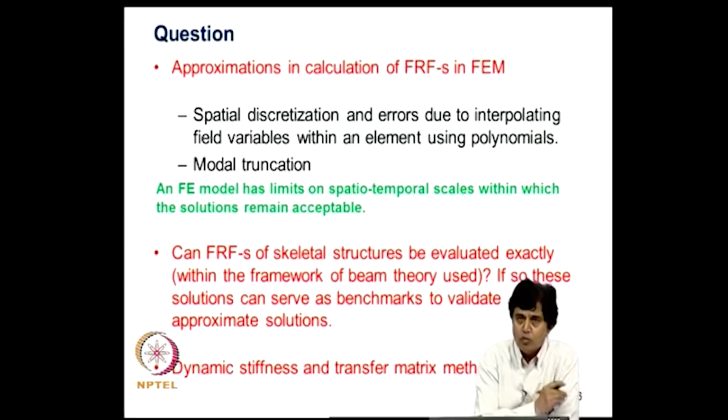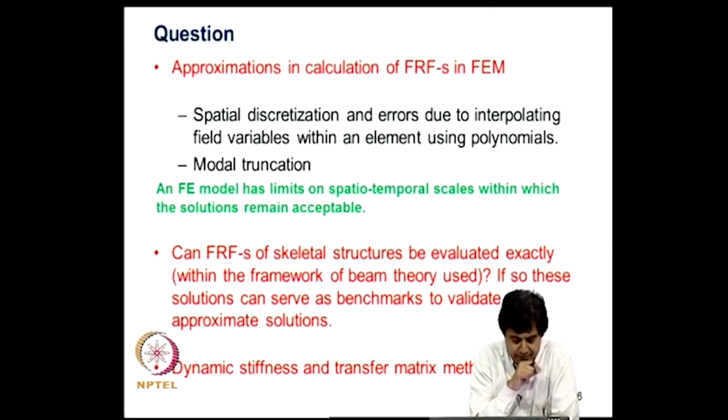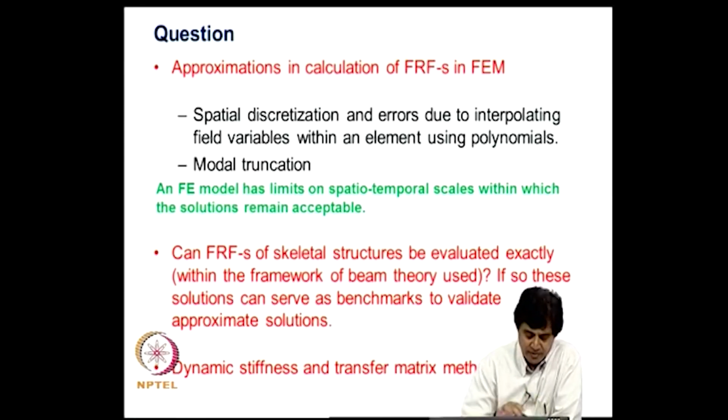Now, we move on to a special topic. We know now that FEM is after all an approximate method. We are using models from FEM, that is the models resulting from application of finite element models in calculation of frequency response functions. Now, there are approximations in this. What are the approximations? There is spatial discretization and errors due to interpolating field variables within an element using polynomials.